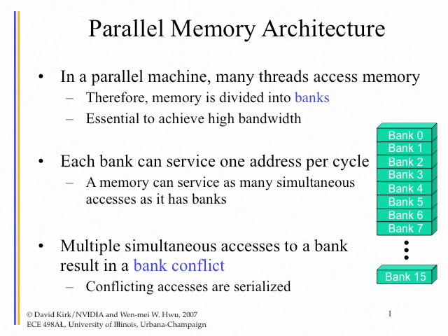What people do is a banked implementation. Essentially, in order to support 8 ports, I actually do something like 16 banks, and I'll talk about why. These banks can each only serve one access at a time. So I really don't have this 8-handset situation. Each person only has one handset in front of him. So now there's only one handset for you, one handset for you, and so on.